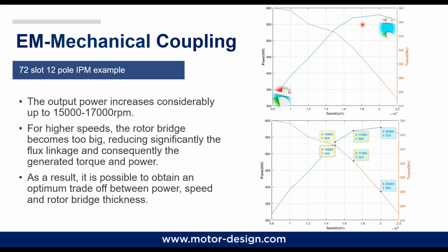If I increase my electric motor speed, I will need a bigger gearbox, which is going to be heavier. So in this case, it's important to think that if I have just a small increment in the power, it's probably not worth increasing the speed anymore, because I'm making the system more complex.